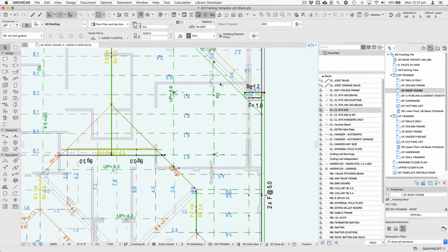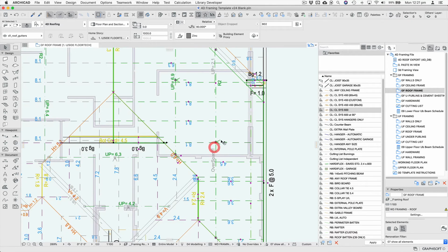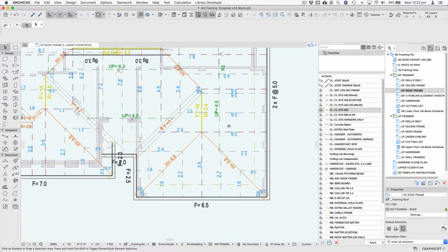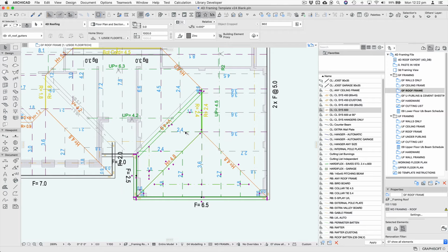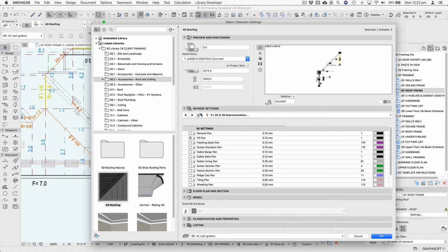And through here, that underpurlin is overspan. Here's the join for the underpurlin. I'm just going to put it over that wall. Now we've got a 4-5 and a 5-4. So that is looking pretty good. Next I might put 1 row of underpurlin around this section of roof.